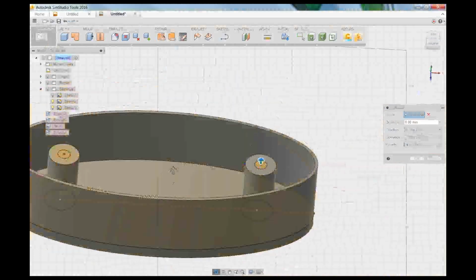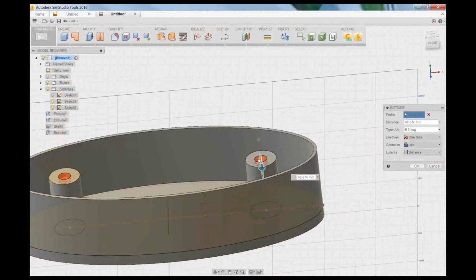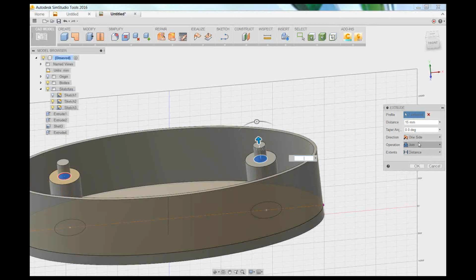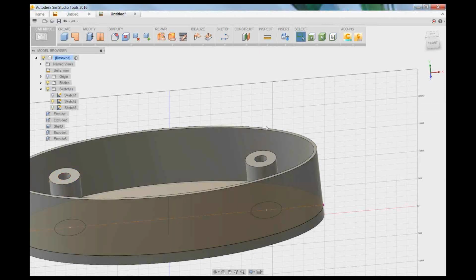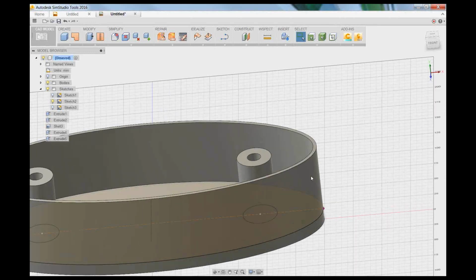So you'll notice that if I go up, I'll be extruding this. But now if I pull down into the feature, you see how everything turns red? Now I'm actually using the cut command, so I don't really have a separate command for these. I can just use the same thing. So we'll go ahead and cut into that. Whoops, negative 15 millimeters. Perfect.